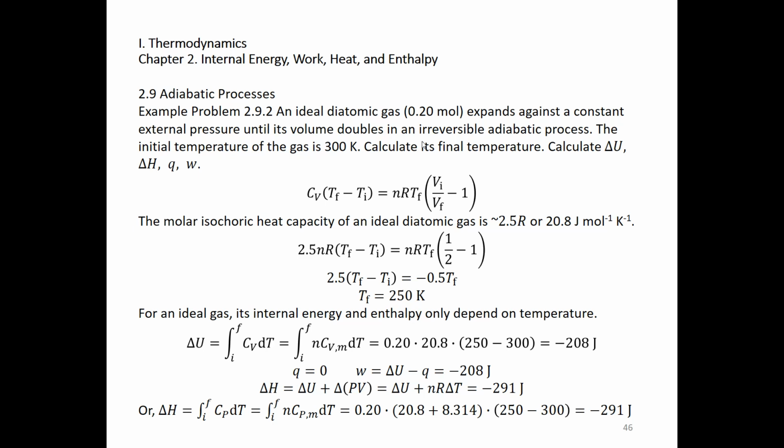How do we compute the change in enthalpy? Again, two steps. The first step has to be isobaric, and then you can calculate delta H. Delta H is simply Q sub P. That's just the integral of Cp dT. Alright, we just calculate that step, isobaric. The second step, make sure it's isothermal. If it's isothermal, delta H is just 0. So overall, delta H is still the integral of Cp dT. So this is a trick to compute delta H and delta U for an ideal gas. Do not do that for solids and liquids.